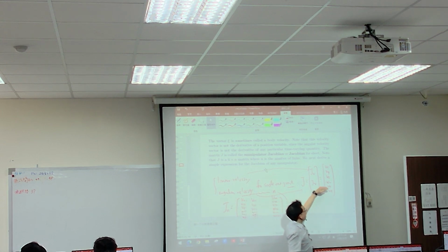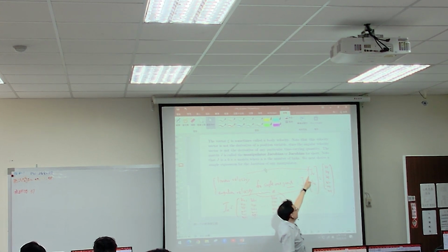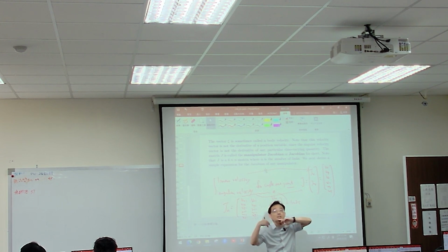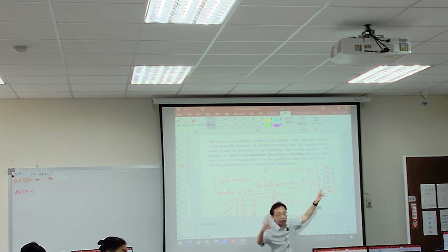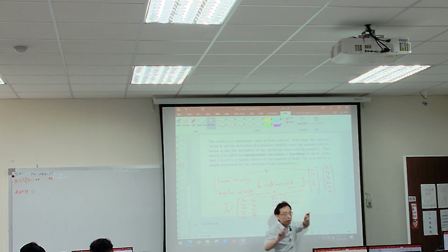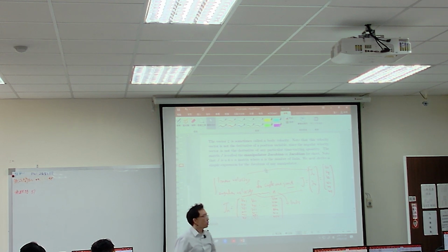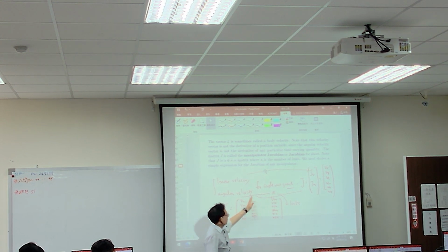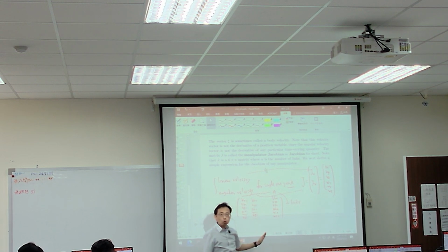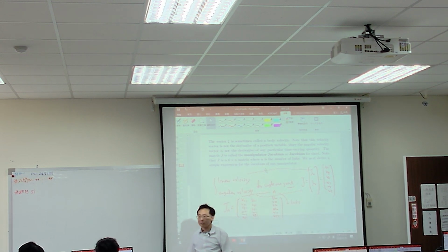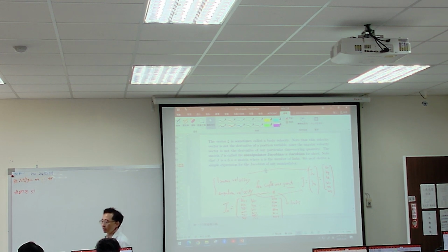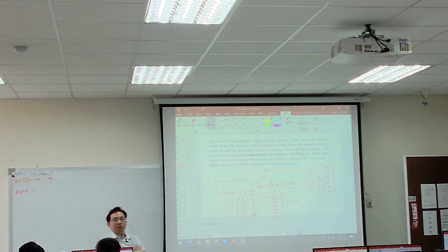Rephrasing again, the upper 3 are for linear velocity, maybe x, y, z. This is my assumption; it should be q1, q2, q3. The bottom ones are rotation. They describe the rotation quantity, so it's omega x, y, z. This is my definition. So if you have n joints, you have one column for joint 1, one column for joint 2, up to joint 6. This is the most important thing today. You need to understand this before you leave the classroom.